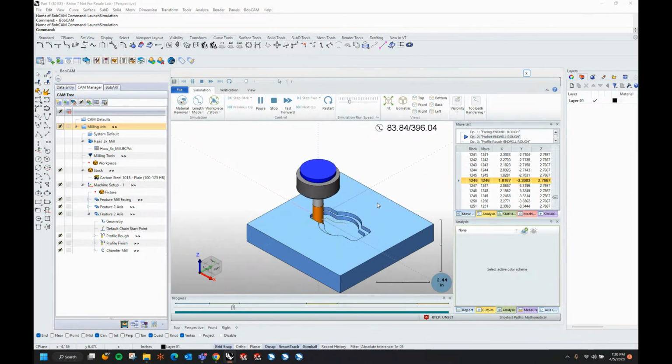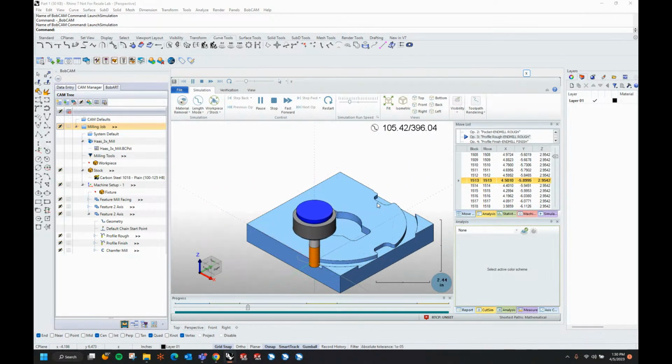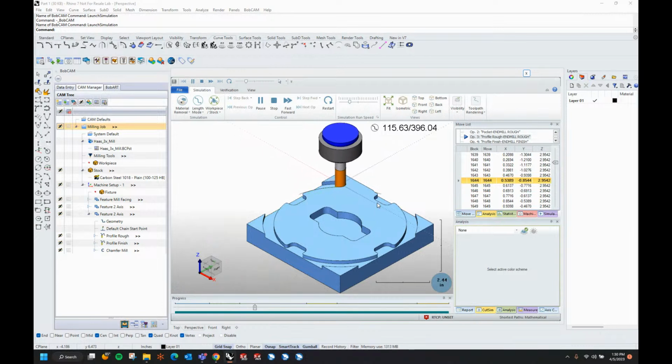Depending on the type of machining you're doing, that may benefit you or not. I know there's jobs that I've had where I've needed to program in the order that I've added the tools, and there's times I've needed to do it by tool number. So it does vary. Just make sure you pay attention to that machining order. We'll take a look at it here in a second when this is done. I'll actually speed it up just a fuzz.